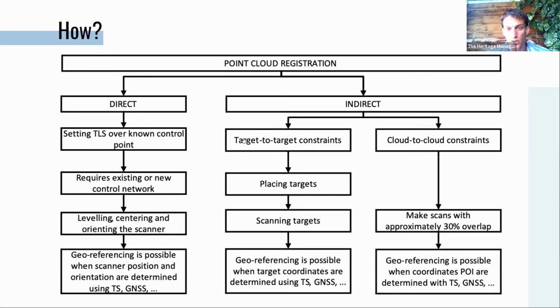So we use the targets that we measure as a basis for our registration. You have multiple targets in one scan, multiple corresponding targets in another scan, and you will make a combination of these targets. That will result in a translation, rotation, and scaling parameter, a scaling matrix, that we can apply on the different scans. And then optionally afterwards, if you have a series of targets that have absolute coordinates assigned to them, you can also have coordinates in a certain coordinate reference system.